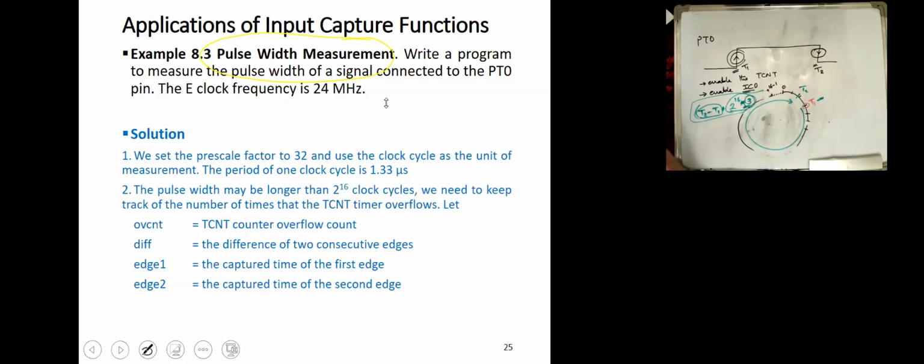But we said last time from the previous example, it's okay if we take the difference T2 minus T1, it is modular subtraction, which means we will count how many times it took us from here to here. Now, what if the pulse lasted longer such that we have another overflow? We will take this time plus 1 overflow time, right?